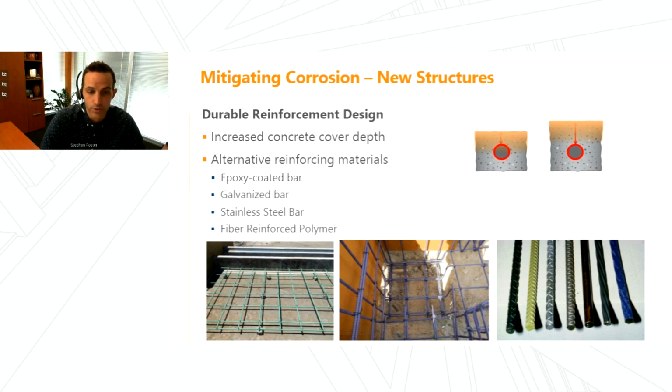But in terms of corrosion performance, adding another protective layer, say an epoxy coating on the reinforcing steel, now provides an additional layer of corrosion protection beyond just the normal passivation layer that occurs in the high pH concrete when it's first cast. The epoxy coating itself provides another layer to help prevent corrosion and slow down that corrosion process.